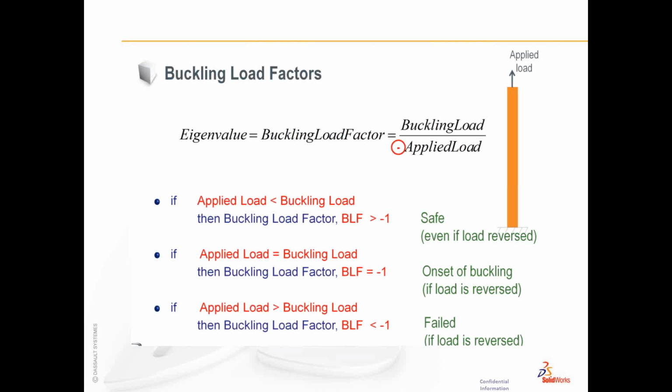If you put that same structure under a tensile load, the natural frequencies increase. And an easy way to think of that is in terms of a guitar string. As you put tension on that guitar string, the note that it creates, or the pitch, increases. As you reduce the tension on it, it goes down. It produces a lower pitch.